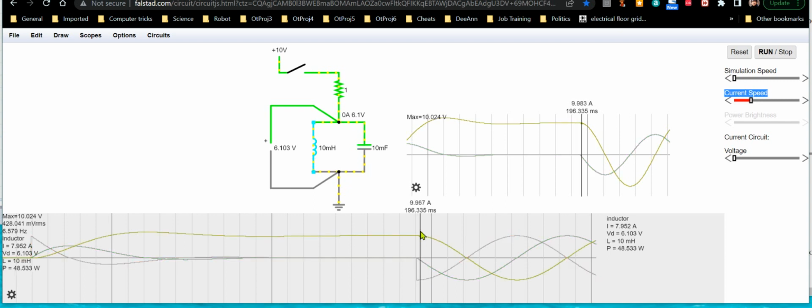But basically that's why you've got equal current here on both sides, but you would have that no matter what, because regardless of the size capacitor we had here, since we had 10 amps flowing through our inductor, it would make 10 amps flow through the capacitor, whatever voltage it had to generate to do that. That's a different subject for right now. But right now, that capacitor is happy with 10 amps and it's charging up at a normal rate.